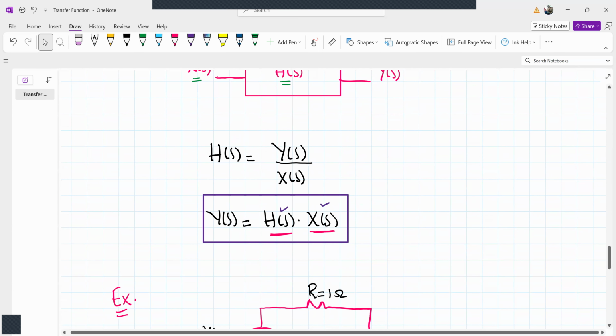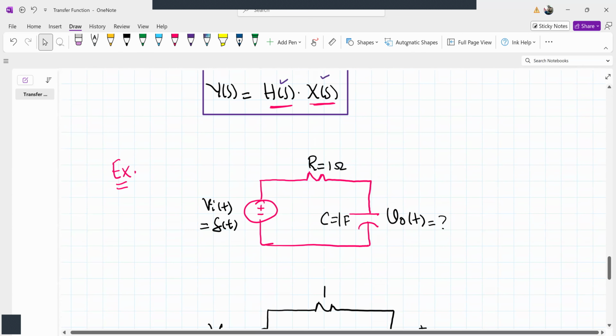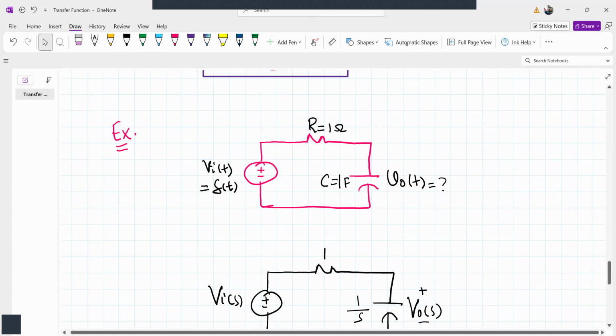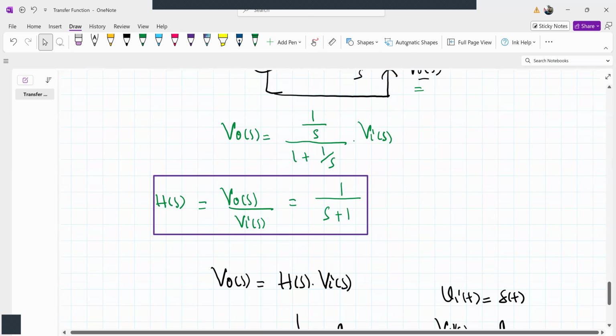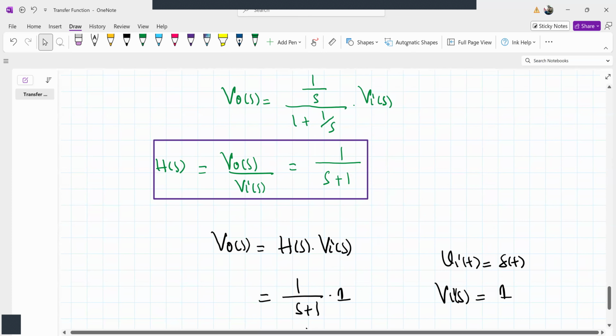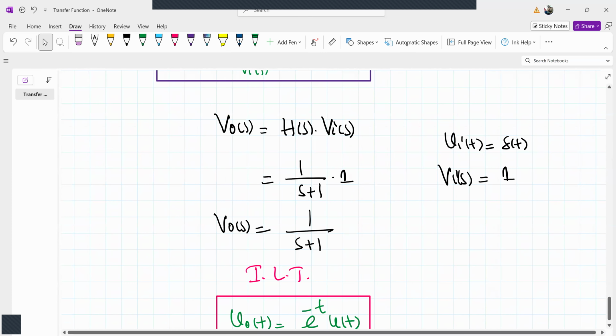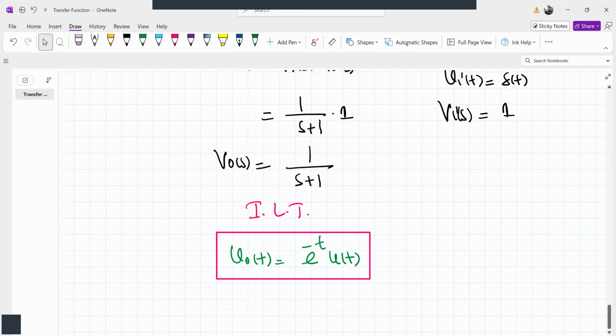This is very important for a signals and systems class. We solved one very simple example, where we first obtained the transfer function, then the output. Sometimes the transfer function will be given, so you have to multiply the input with it and take the inverse Laplace transform. Very easy, if you know how to apply the Laplace transform in networks and the inverse Laplace transform for given functions.